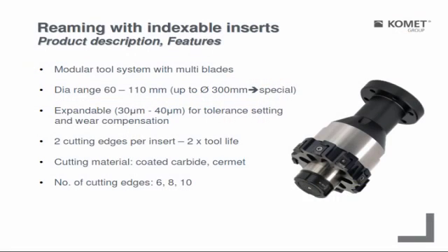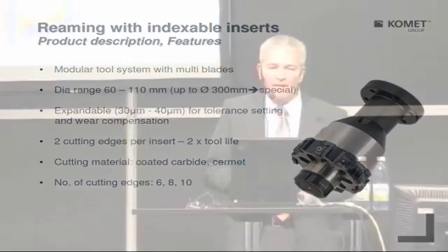Each of these inserts, what we are mounting here, has 2 cutting edges. So this ring has two lives, completely two lives. Standard cutting material, and 6, 8, 10, 12 numbers of inserts in the reamer ring.